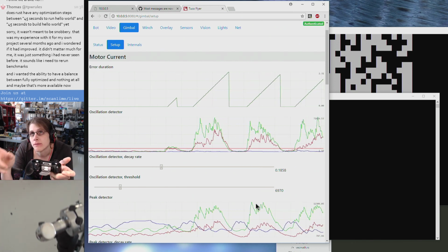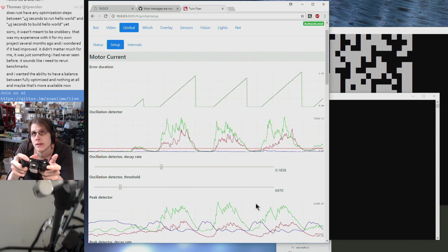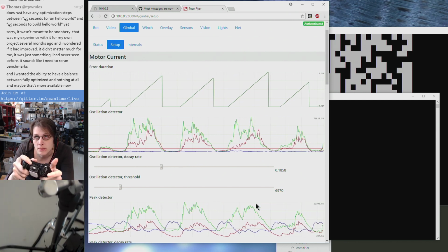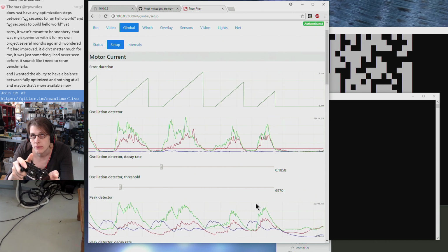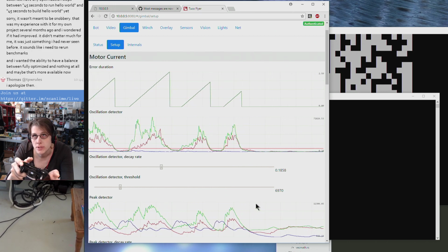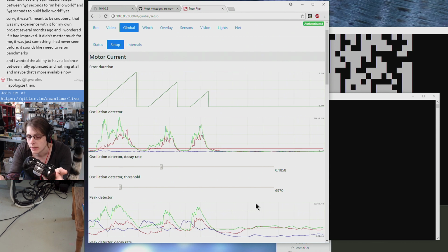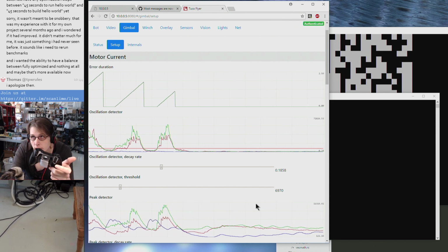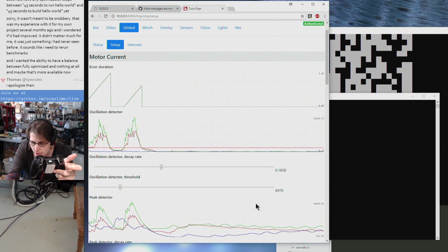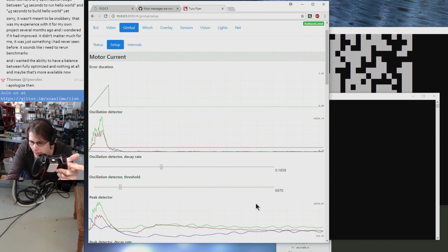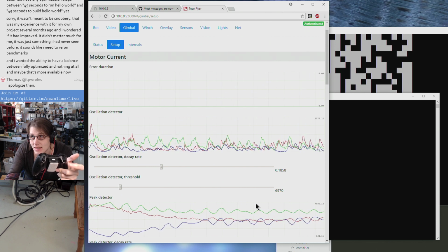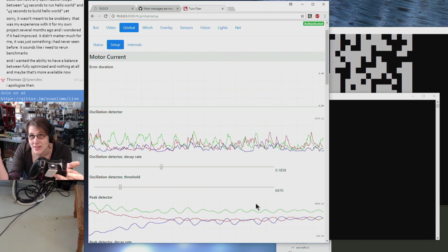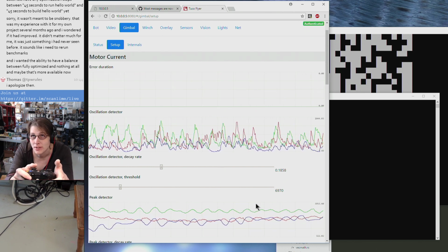We are trying to fix that by just having the gains on the gimbal tuned better. Right now the gains are a little bit better than factory, but still not great, and there is no system for actually recording those and loading them back into the gimbal when it starts. So until that's there, I don't really need to spend time tuning gains because there's nowhere to save those values.